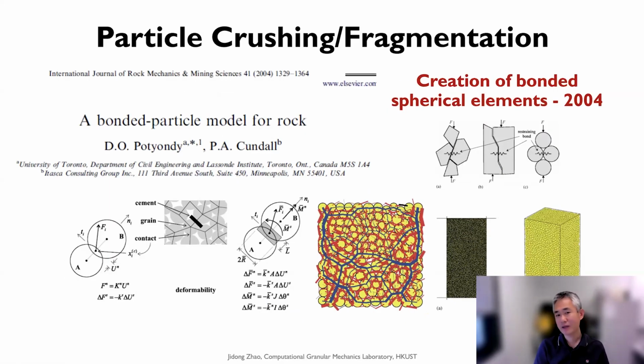And again, Peter Cundall and his collaborators proposed another similar work in 2004. We call it BPM, the bonded particle model, for implementing DEM. Basically, they implement a parallel bond to connect spherical particles together, and this bond can sustain certain kinds of strengths, including stretching, twisting, and compressive strengths.